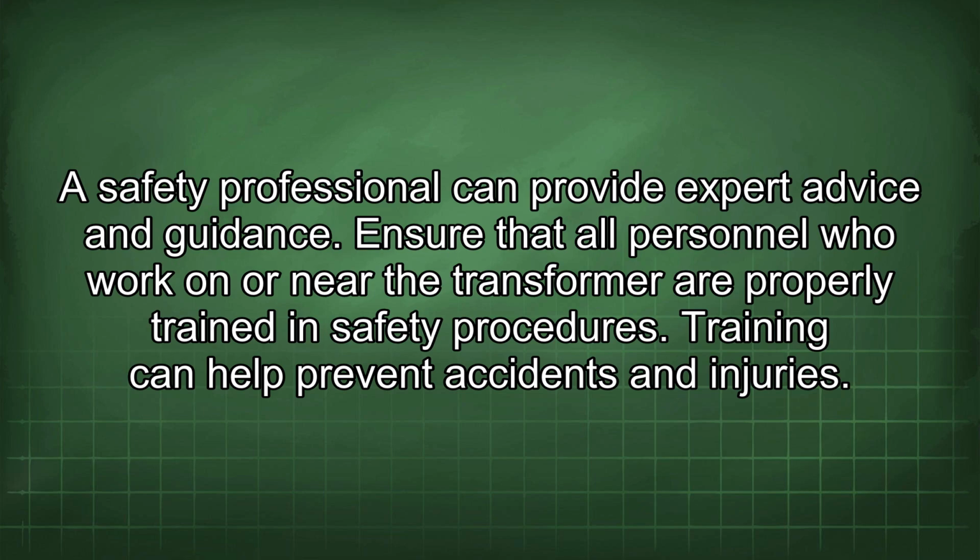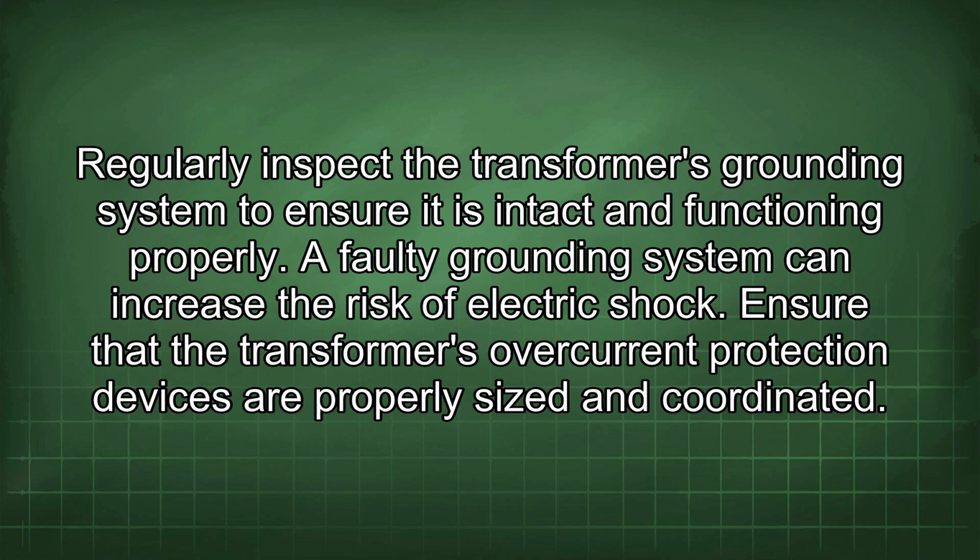Ensure that all personnel who work on or near the transformer are properly trained in safety procedures. Training can help prevent accidents and injuries. Regularly inspect the transformer's grounding system to ensure it is intact and functioning properly. A faulty grounding system can increase the risk of electric shock.